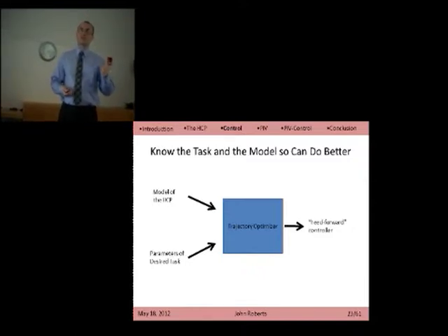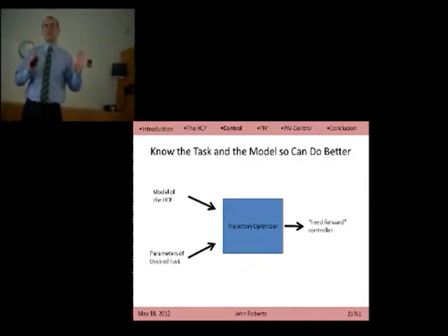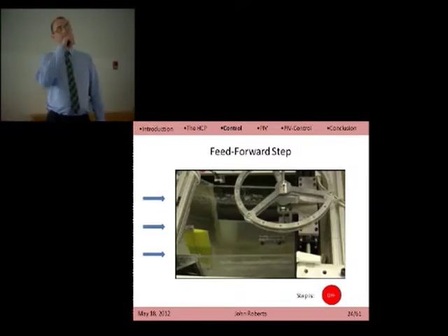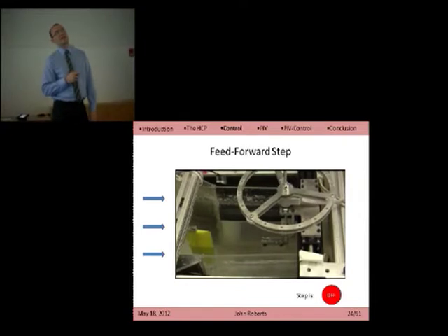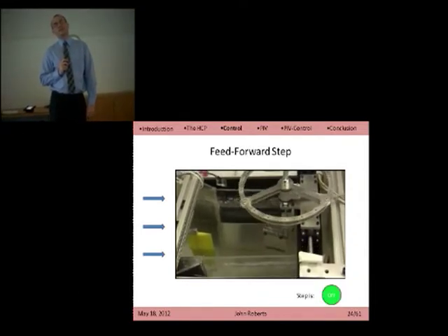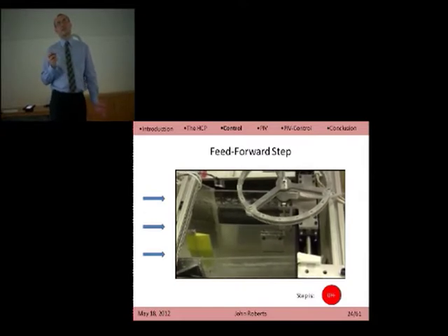Whereas the feedback controller, you can turn the gains up, but at some point it actually destabilizes, and I push them up as much as possible. So just making the feedback controller higher gain is not a way of solving this problem, but this feed-forward one actually is. So we can design this feed-forward trajectory, execute it. Once again, you'll see the step turn on. This one's much more obvious in the video, though. It'll suddenly turn on, and you'll see it kick there pretty quickly. So that's nice, but it overshoots heavily, if you see that.